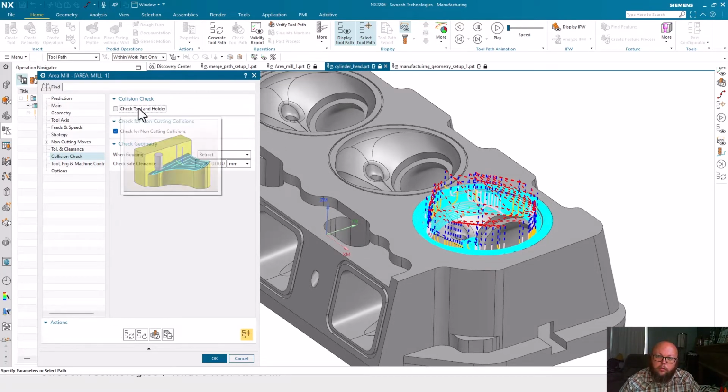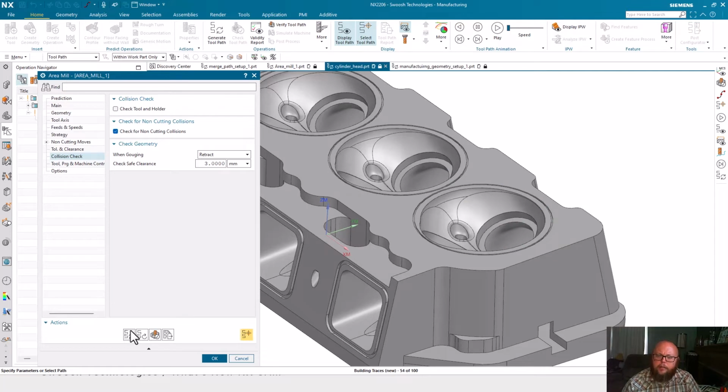Well, I want to ignore that setting. I want to go ahead and generate a toolpath all the way throughout that region, even though in this particular scenario, our holder is going to gouge the part. But I'm going to use the functionality tilt tool axis to clear our holder from the part geometry after the fact, after the actual toolpath has been generated. So essentially we're going to be transforming this from a 3-axis toolpath into a 5-axis toolpath. So once the toolpath generation is complete, we'll be able to go to the next step, which is going to be tilting this tool axis and providing the clearance we need for this particular operation.